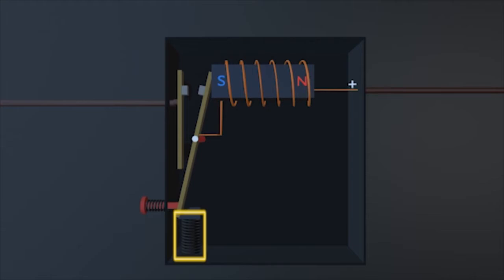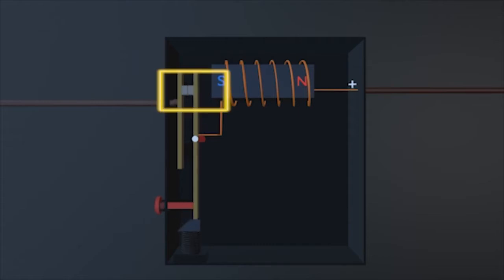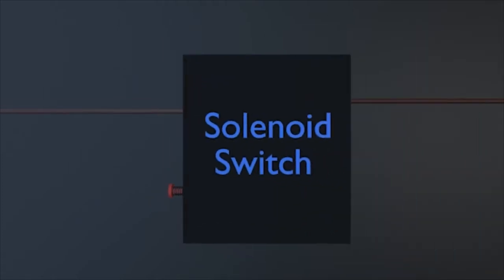The springs help to maintain the position of the armature, since the electromagnet won't attract it after the circuit has been broken. So after the amount of the current flowing has been adjusted, you can reset it manually by pressing the reset button. This resets the position of the contacts, thus completing the circuit again.